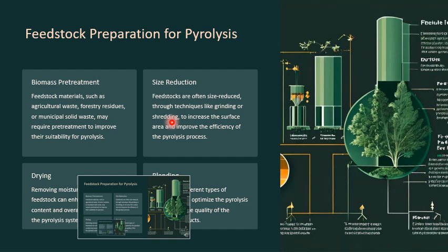So as you increase the surface area, there's more contact per unit of length, and that also improves the pyrolysis process. And drying is removing the moisture from the feedstock, and that can also enhance the energy content and the overall performance of the pyrolysis system.